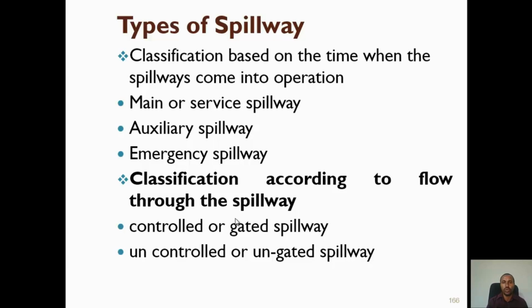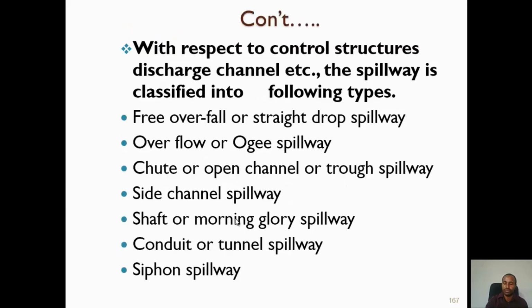With a gated spillway, you may close the gates and then, when required, open them to release water to the downstream part of the dam structure. Or it can be uncontrolled, simply overtopping without gates. But the spillway crest level must be lower than the crest of the dam structure, which is at normal pool level.